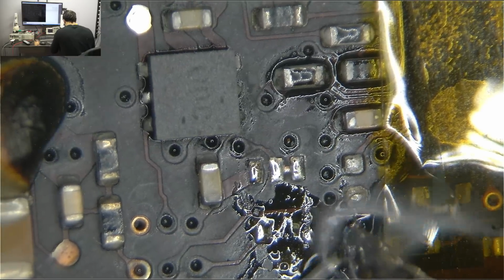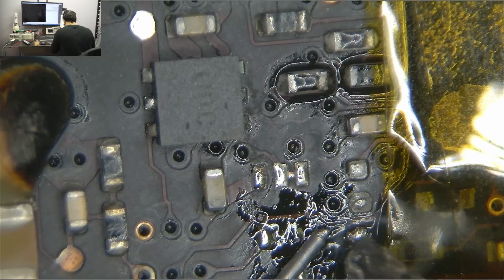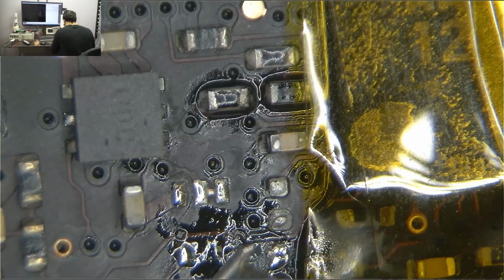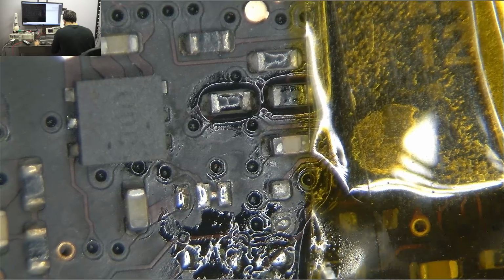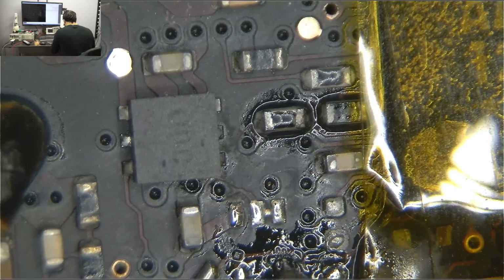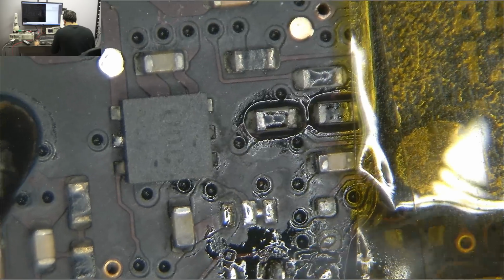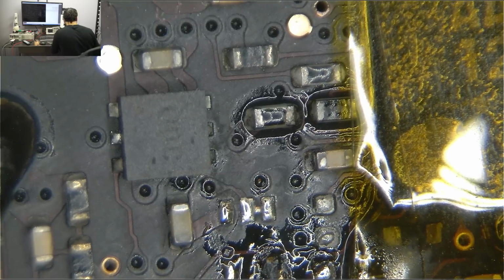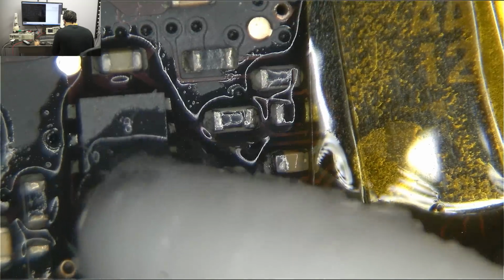We're just going to etch away a little bit of the copper on the board. So see what I'm doing here? I'm trying to etch away at the copper on the board so I can make space to put some solder. See that? Now we're going to do the same over here. Sometimes it's just totally burnt and there really is nothing you can do, but sometimes it isn't. And so on the pad for the capacitor, the etching worked. On the other one, there's nothing that I can do.